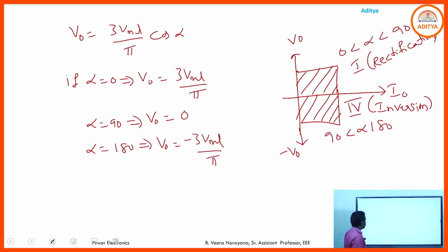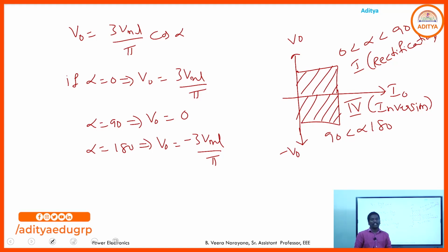So this is a simple representation of a 3-phase fully controlled converter with RL load. Where we use this full wave controlled converter means if you want to collect 2-quadrant operation, like first quadrant and fourth quadrant operations, then we go with the 3-phase full wave converters. If you want single quadrant operation for the entire firing angle range, even with RL load or RLE loads, then we go with the semi converters or half controlled converters. The next one is the 3-phase semi converter or 3-phase half controlled converter.